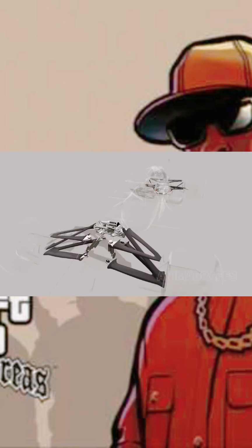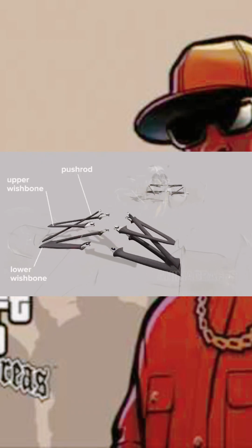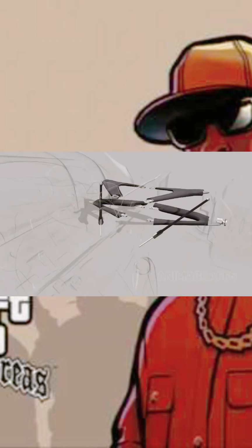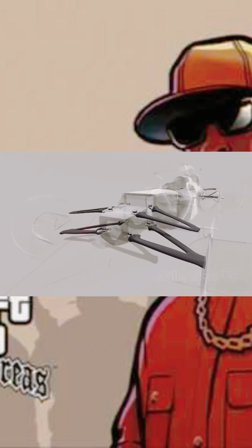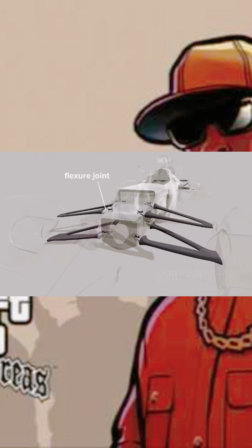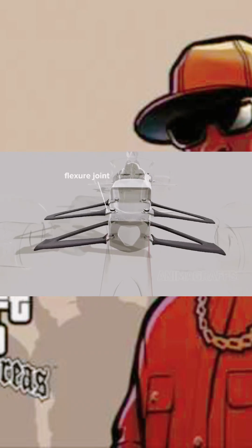Suspension. Both front and back suspension setups share similar components: upper and lower wishbone arms with a push or pull rod. The wishbones are rigid structural supports with limited vertical travel. At the front, where heat isn't an issue, wishbones are directly attached to the monocoque and have simple flexure joints designed to bend under load.